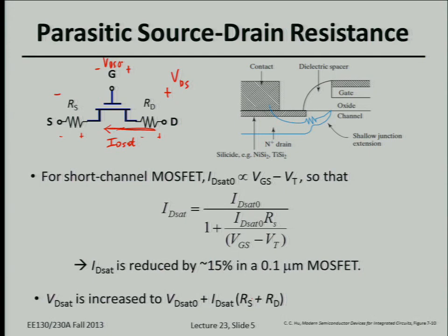And so basically, just qualitatively, assuming that this is a short channel MOSFET. Why is this more of a problem for short channel MOSFETs than for long channel MOSFETs? That's right. So as Will said, when the channel length gets really short, then when the transistor turns on, the resistance is relatively small. For a long channel device, because it's longer, it has a larger on-state resistance. So the source and drain regions, even if they have some resistance, is kind of small compared to the channel resistance.